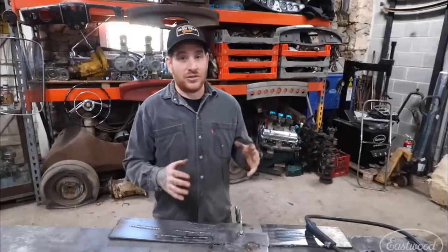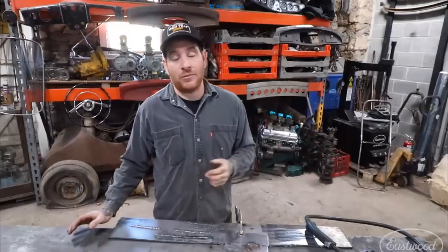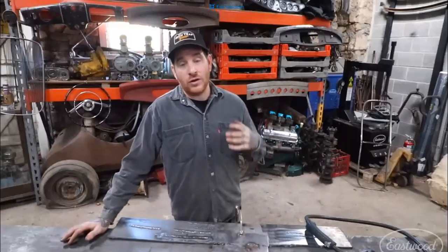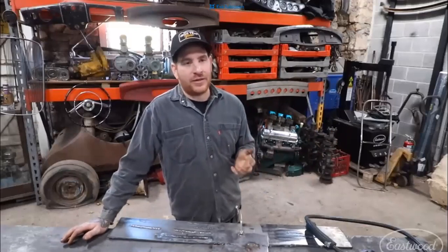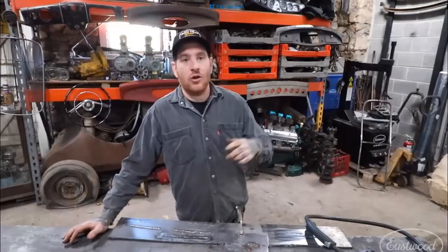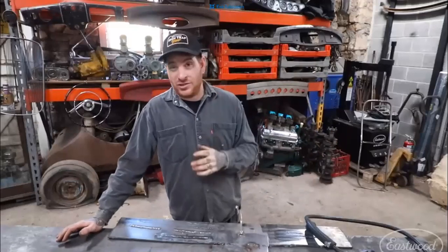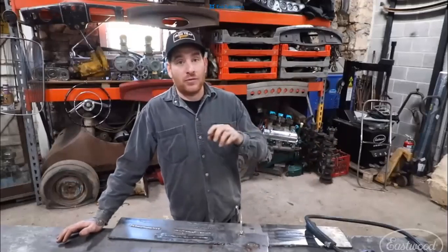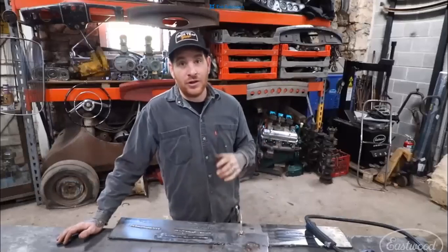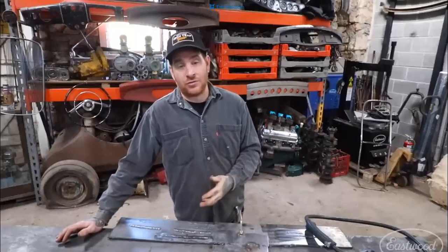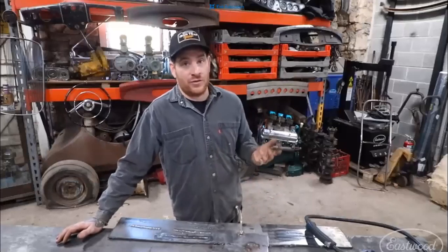Another issue at the source within your building or shop where you're welding is if you have poor or old wiring. If you have an electrical system where maybe it's piggybacked from your house or from another source, or it's just really old wiring, there may be a drop in voltage every time it goes through those connections, and by the time it gets to your welder, you may not be getting the power to weld correctly, or maybe your welder won't even turn on.